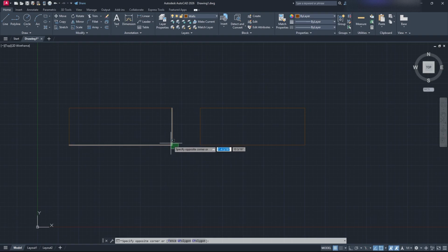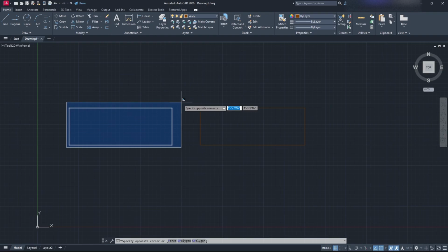I only have to select like a corner of it. If I only do the corner, I'm selecting those two lines. Whereas if I'm doing blue, I can't do that. You can see here, nothing's selected when I'm doing that. I have to fully go over the bottom line to select it. And if I want to select all this, I have to fully go over it. So keep that in mind.